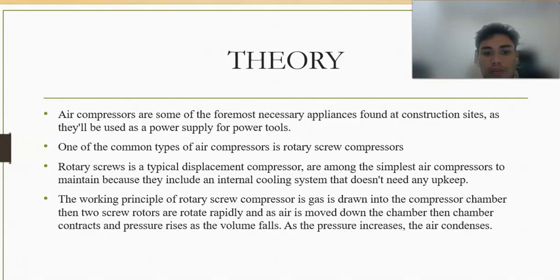The working principle of rotary screw compressor is gas is drawn into the compressor chamber, then two screw rotors are rotated rapidly, and as air is moved down the chamber, the chamber contracts, and the pressure rises as the volume falls.